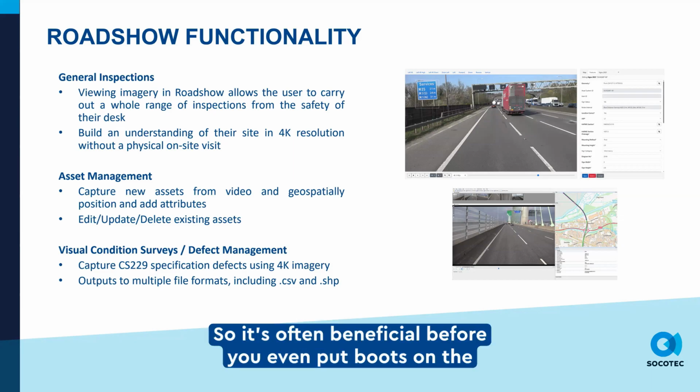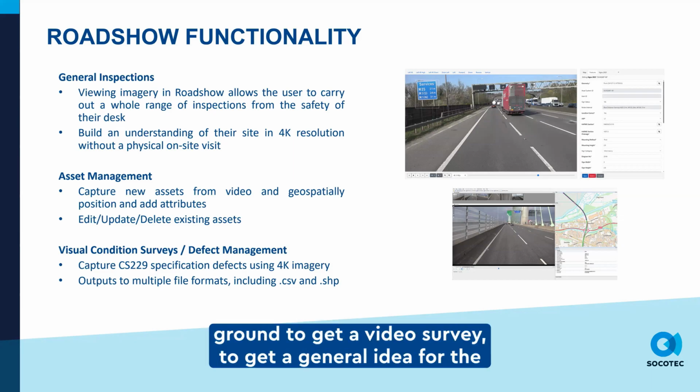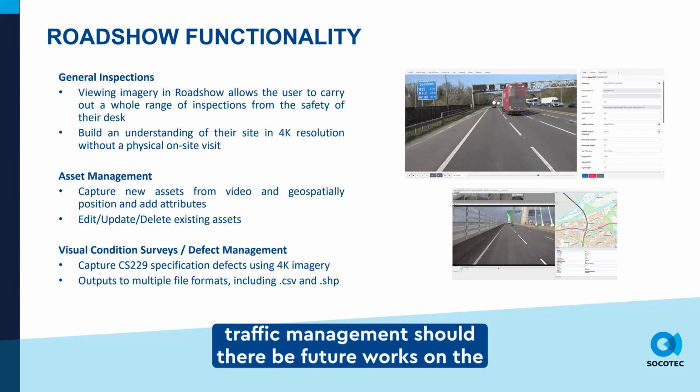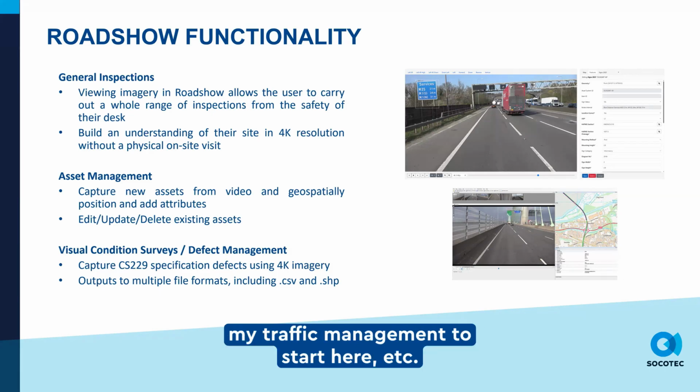It also helps to build a digital understanding of the site. It's often beneficial, before you even put boots on the ground, to get a video survey to get a general idea for the site. It can also be handy for passing on instructions to traffic management should there be future works on the scheme. You can simply crop out a screenshot and send it to them: I want my traffic management to start here, etc.